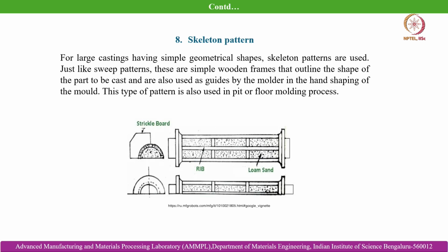In this case we do not create a complete pattern, that means a complete replica of the cast object, rather we create a wireframe kind of model, which provides enough structural integrity to that large pattern for the large castings, and then we create the rest of the cavity within the mold itself, after getting the skeleton made with the help of the skeleton pattern. So, this is useful for very large castings.